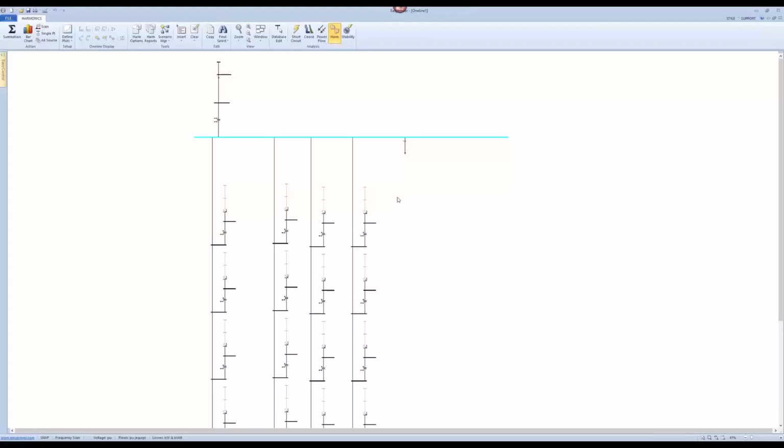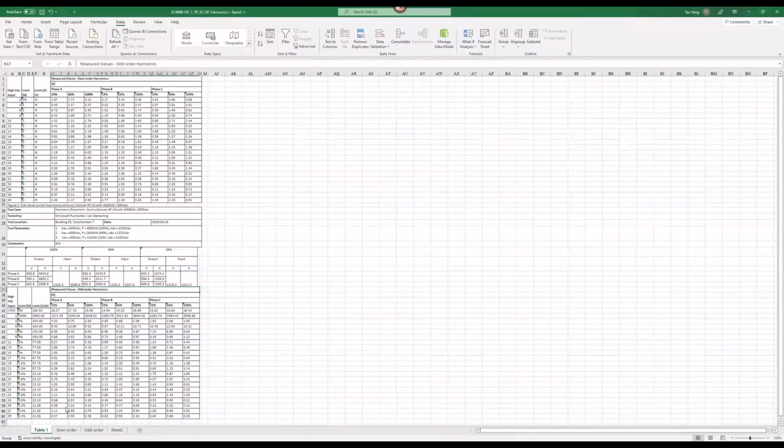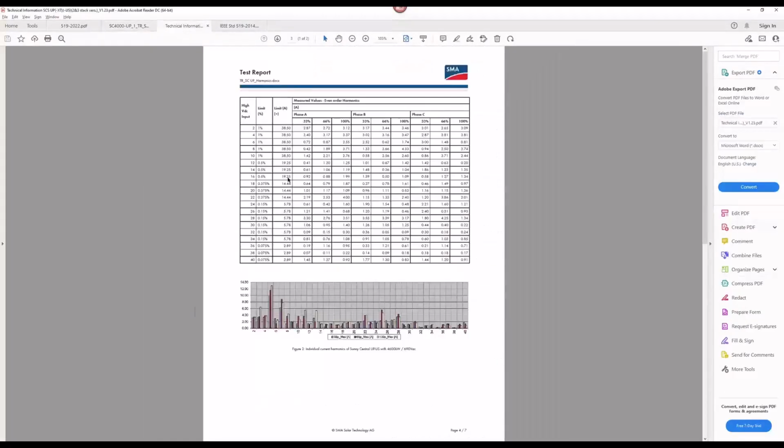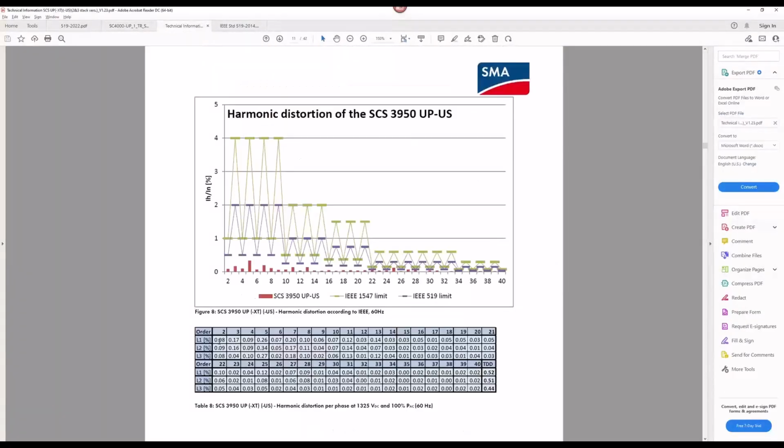I know that many of our clients use PSCAD, EMTP, those kinds of time domain software to evaluate the IBR, to build an IBR in the PSCAD model and run the harmonic analysis or even other analysis, which is accurate, but you don't have to do that if you obtain this table, right? Most importantly, this table, and also the injection table here as well, about the designed harmonic injection level at a particular harmonic order. If you have this, you've got all you need to use EasyPower to finish this job within maybe just a whole morning or afternoon, you'll get it done, right?